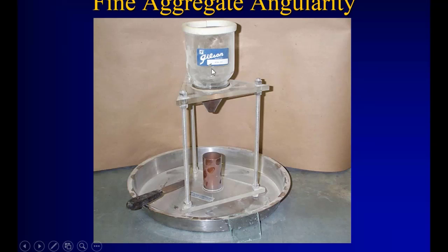This little sample container here is placed. This is about 115 millimeters, the height of this, which is about the height of a gyratory plug as well. And then you have this little calibrated container down here. I like to call it the brass shot glass. And we calibrate that because now we can get a known volume in that cup. And of course, we have a tare weight of that cup. And essentially, you hold your calibrated finger over the funnel here, put your material in here. Gravity does the work and drops it 115 millimeters into this cup. And takes very little time.